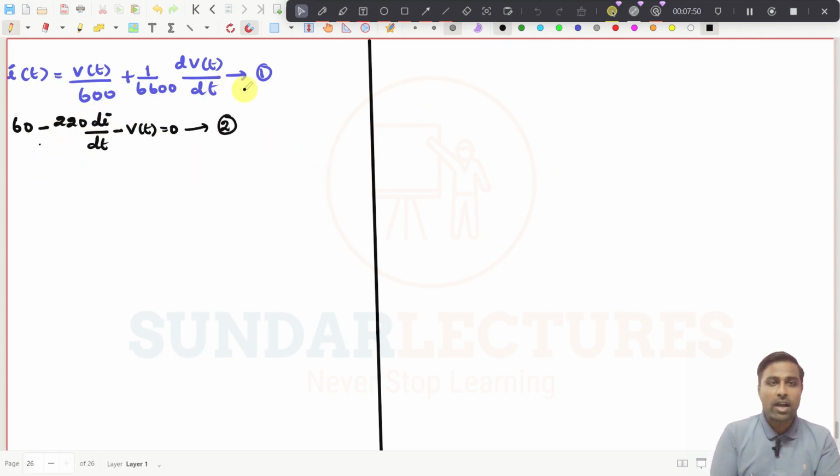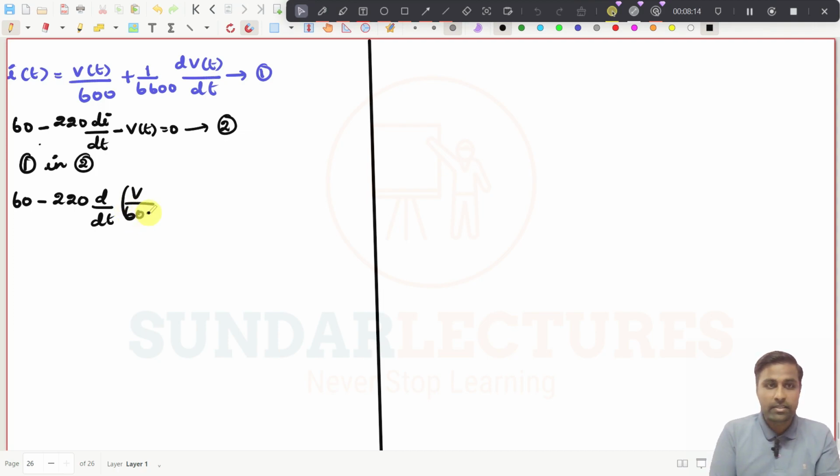Now I can substitute expression 1 into this I of t. So what I will get is 60 minus 220 d by dt of this I of t. I am not going to write V of t, I will write it as V. So V divided by 600 plus 1 divided by 6600 dV by dt, and this minus V will be there, that should be equal to 0.